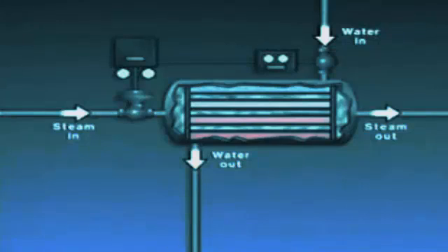However, there are many possible disturbances in a process, and a typical feed-forward control system may not be able to respond to every one of them. For example, the feed-forward control system that we just looked at responds only to changes in the temperature of the water entering the heater. Other disturbances, such as a change in the pressure or temperature of the steam entering the heater, can also affect the outlet water temperature. But those disturbances will go unnoticed by the feed-forward control system.